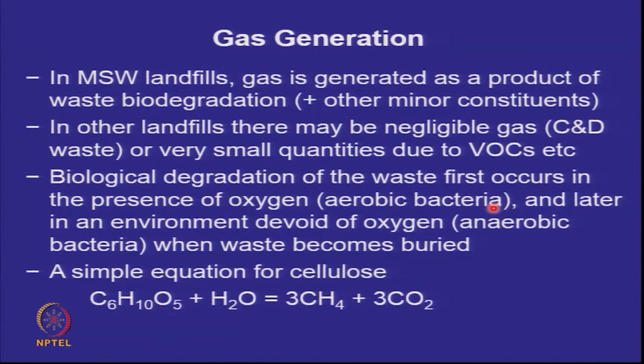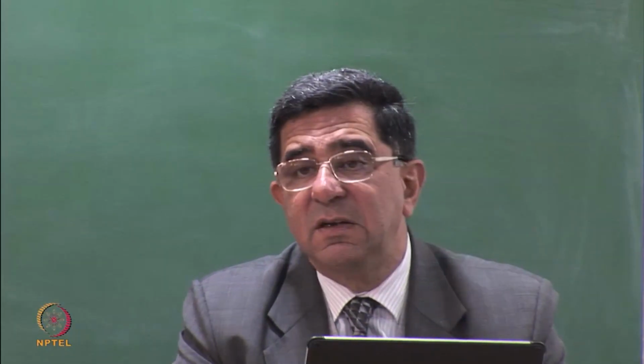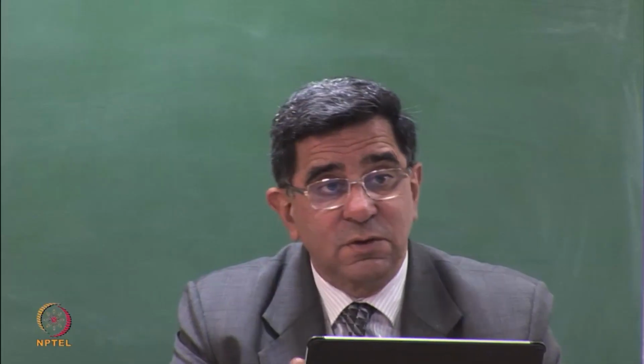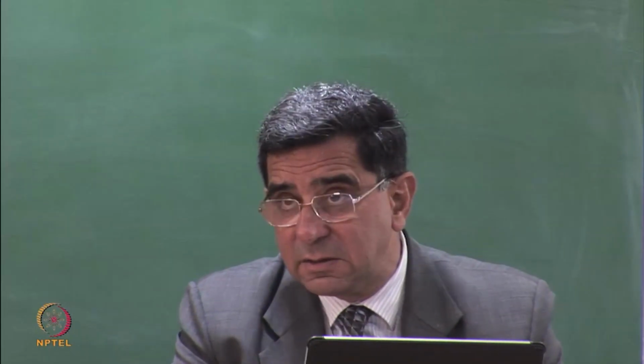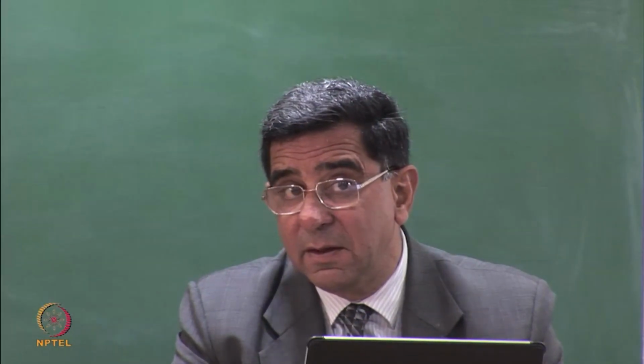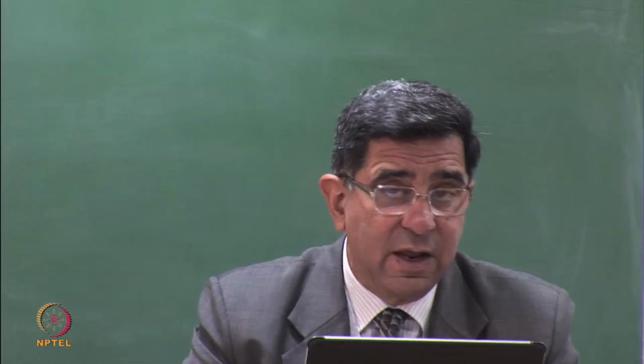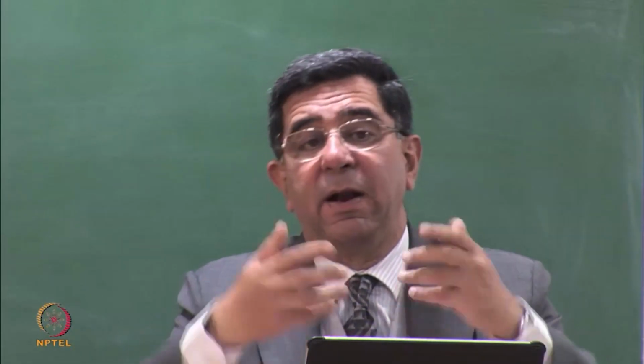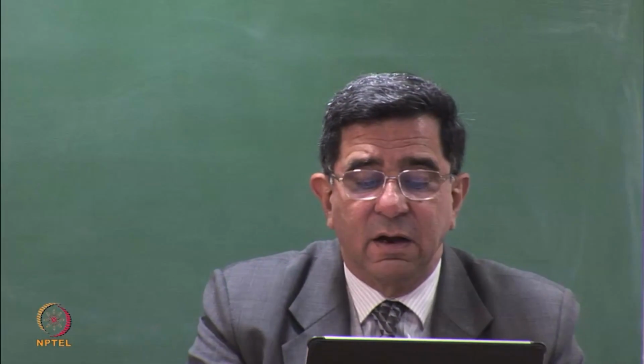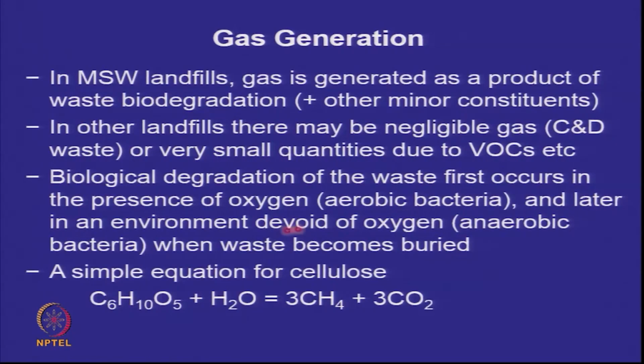But the waste fills up rapidly in a landfill. So once the initial oxygen is removed or utilized, then no more oxygen comes in, because you're putting a daily cover, a soil cover at the end of the day, and the waste gets buried. So later anaerobic bacteria take over and we have anaerobic degradation.